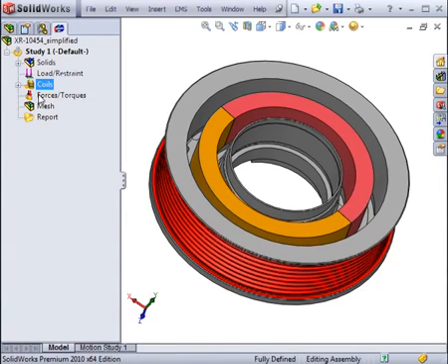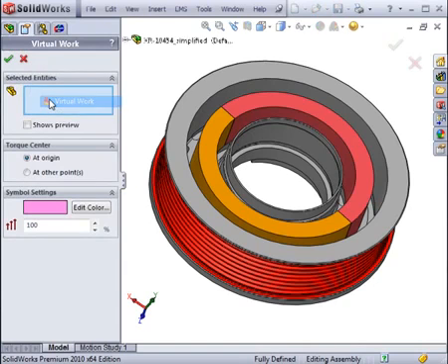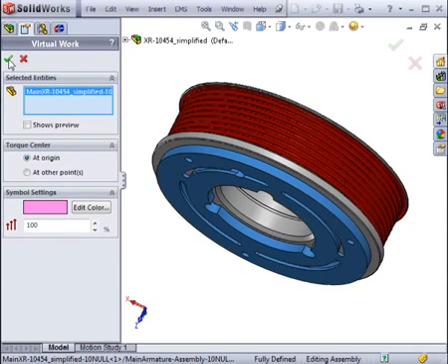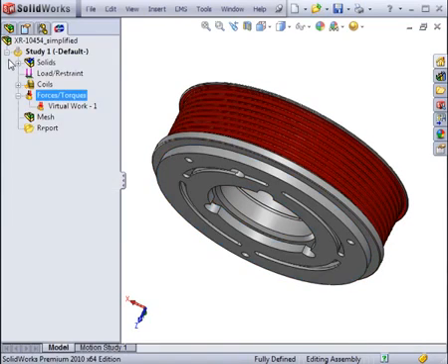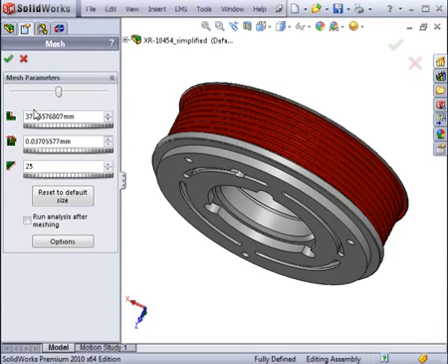After creating the coils, the user can request to calculate the force or the torque acting on the steel armature. Simply select the armature and specify the torque center. The finite element mesh has to be defined. Simply by creating the mesh, specifying the average number of elements that the user wants across a body, or specifying the global element size, a mesh can be generated easily.